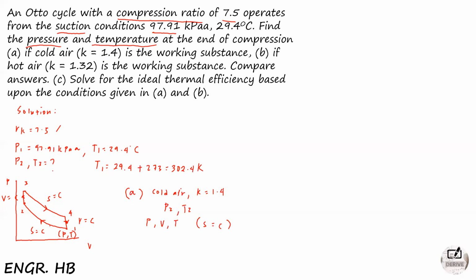So, to make it easy to remember, we're going to have a basis or reference. We will use pressure as the reference, so that was the ratio of two pressures. Please remember this formula: pressure 1 over pressure 2 is equivalent to volume 2 over volume 1, raised to K. Our K is 1.4. And of course, we have the temperature T1 over T2, raised to K over K minus 1.